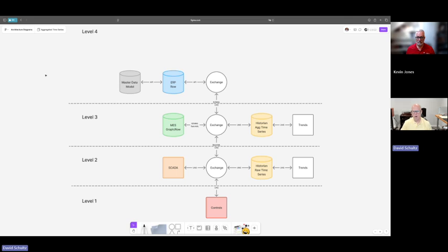So what we want to do at level 3 is start aggregating some of that time series data, or downsampling some of that data. As I mentioned earlier, we're going to have that 1 second data or even 500 millisecond type data that's going to sit in that raw time series historian. We may want to have a 10-second sample rate, or even something slower, depending on the application that is sitting in this level 3 area that is going to be used by other systems.